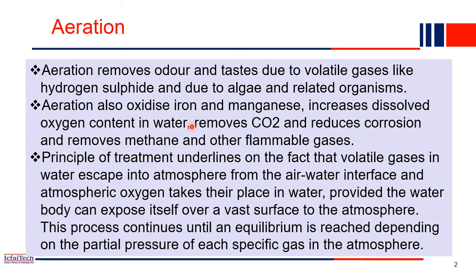Aeration also oxidizes iron and manganese, and increases the dissolved oxygen content in the water. So basically in the aeration process, the dissolved oxygen content will be increased, and it removes the CO2, carbon dioxide present in the water, that will be automatically removed. It reduces the corrosion and removes the methane and other flammable gases.